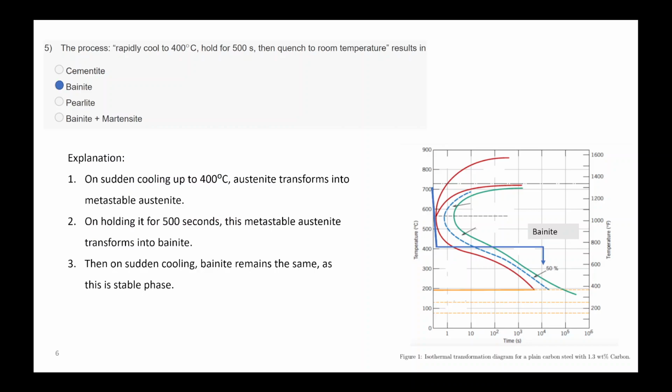Okay. Ma'am, and there was another slide on fracture mechanics. Failure occurs when the stress plus crack geometry is greater than the material fracture toughness. And for strength of materials, failure occurs when the stress is greater than the material strength. By strength of materials, we mean the analysis of beams and those things. So if the stress is greater than the yield strength, then it will be a failure.